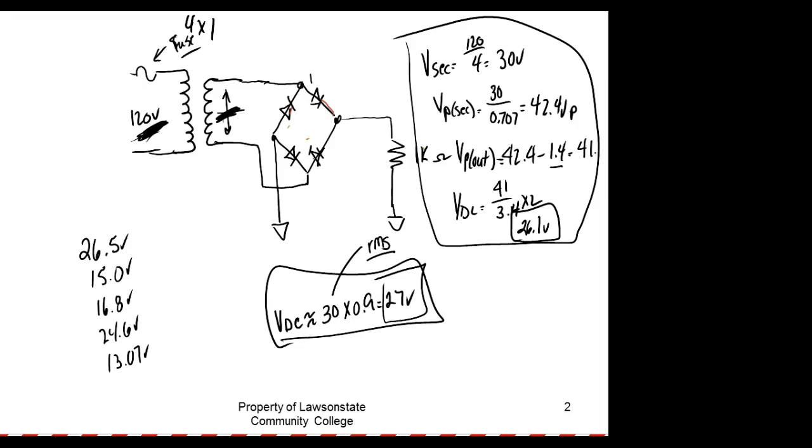And by the way, a lot of transformers don't even give you the division ratio. It gives you an input voltage and an output voltage. What you've got to understand is if you don't use those voltages, you're going to have to know the division ratio. And I've seen that done a lot of times. So they might say, okay, if I put 440 on the input, I get 120 out. Well, see, that would be a divide by 4. So I can get the ratio, that's a divide by 4.